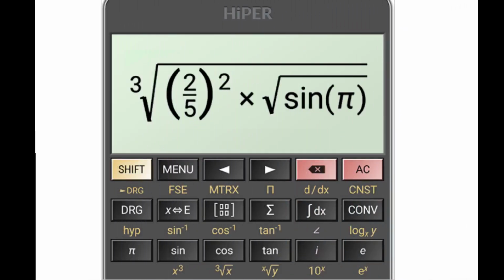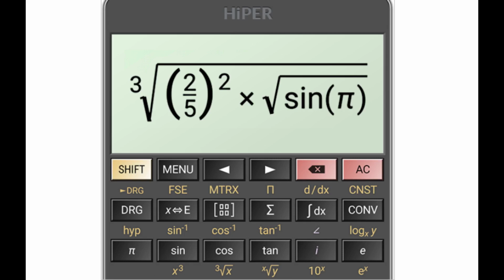The early calculators used hundreds of germanium transistors, which were cheaper than silicon transistors, on multiple circuit boards. Display types used were CRT, cold cathode Nixie tubes, and filament lamps. Memory technology was usually based on the delay line memory or the magnetic core memory, though the Toshiba Toscal BC1411 appears to have used an early form of dynamic RAM built from discrete components. Already there was a desire for smaller and less power-hungry machines.